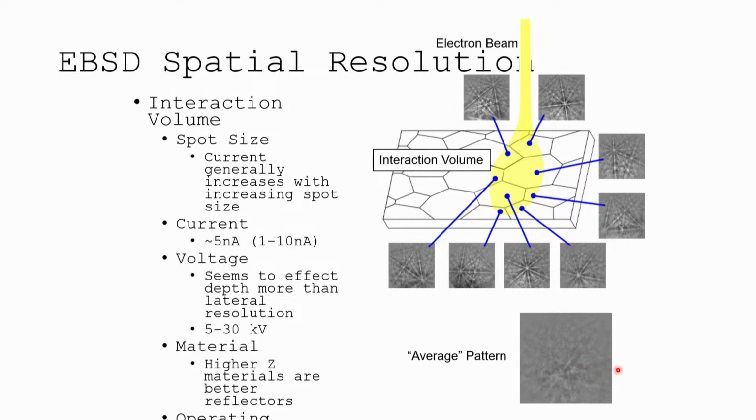A lot of times I'll look at a pattern that my students show me and they'll say, I'm not getting good diffraction. I'll say, well, I see two patterns in there. Here's one orientation, here's the second orientation. This one I'm seeing some bands through here and maybe some down through here. There might even be a third one, but it's hard to tell what's going on. But a lot of times you can say, I'm getting diffraction from more than one grain. That means either your grains are too small, or your beam maybe is too wide, maybe you have too large of an aperture, too long of a working distance, too much beam energy, right? Maybe you decrease your beam energy, maybe you'll have less interaction volume. There's a lot of things you can think about how to do that.